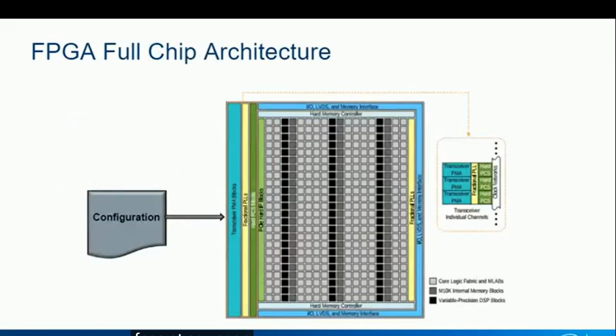This slide illustrates the organization of a typical FPGA chip. This device includes programmable I/O, programmable core logic, programmable memories, and programmable DSP blocks. DSP blocks perform digital signal processing functions with high-speed multipliers and adder logic. The inset shows an expanded view of the serial transceiver block that is used in many common high-speed I/O standards. External to the FPGA is a configuration device, which is usually a flash memory that contains the settings for all of the programmable functions within the FPGA part.